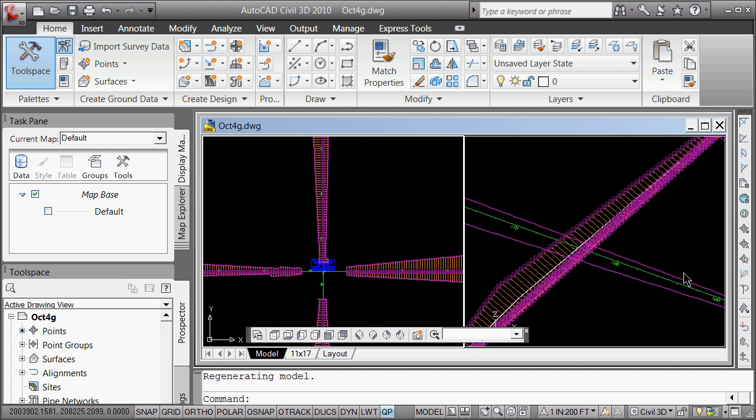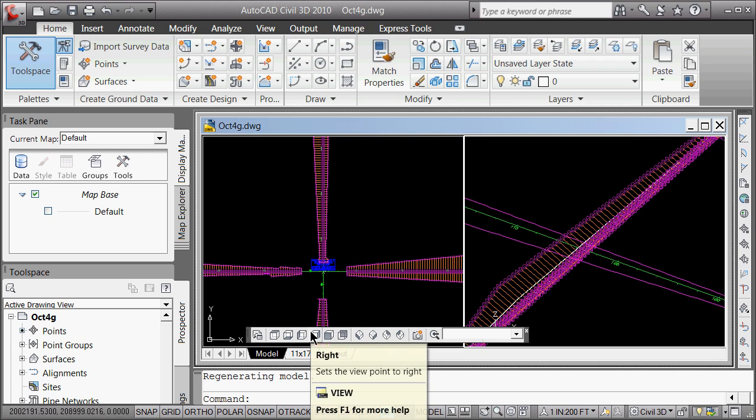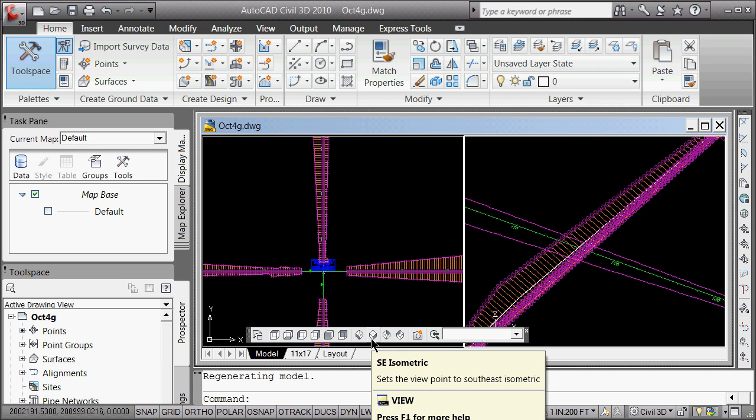Alright, so we have 2D world, 3D world. And just to review, now that we've got these, basically this is a 3D world as well, but this is actually seeing it from above, or from a kind of an isometric view. I'm going to caution many of you against getting too used to just using these views until you understand what they're doing with your user coordinate system. We'll see how that goes. I have had, and it may be just a setting thing, some issue if you're trying to use coordinate systems and these views, in that each one of these goes ahead and changes your coordinate system as you switch the view.